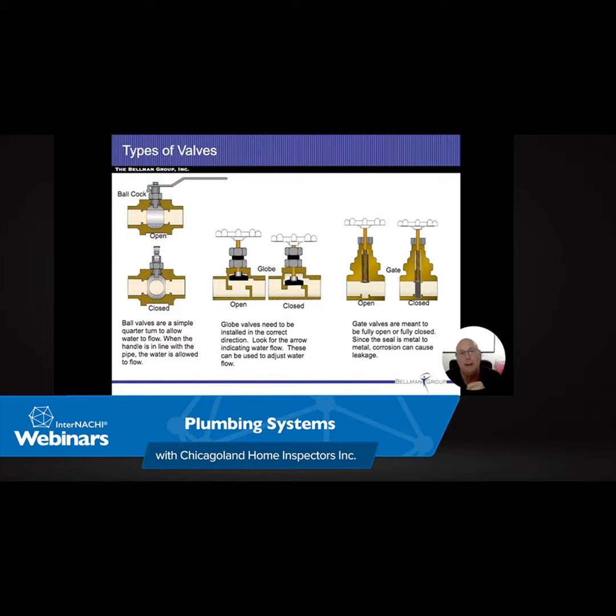All right, causes of broken trap seals. Most common cause we're going to run into would be a negative pressure or aspiration. So here they're showing a large flow of water from the toilet. We're not vented properly with the sink or the laundry tub or something else that's nearby. That's going to create a negative pressure and siphon out that water in the trap. Once the water's gone, then air is going to be able to come back up. All right.